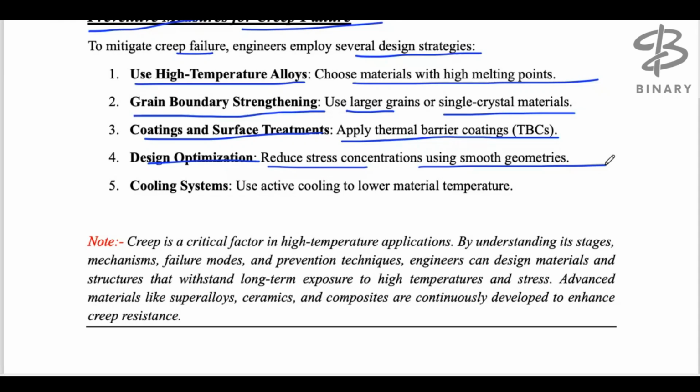So how can we reduce the stress for the same loading? We are not increasing the load. If your design is very rough, or has notches, then it will fail much earlier for the same loading. So what we can do is make a smooth design that does not have any notches. In other words, the design must not contain any stress concentration areas.